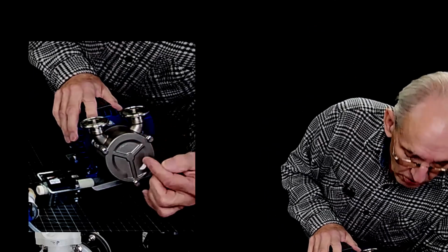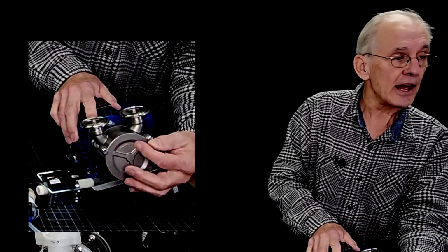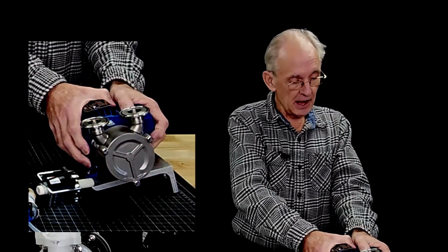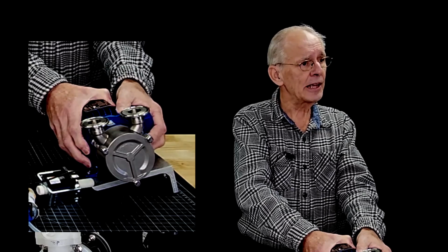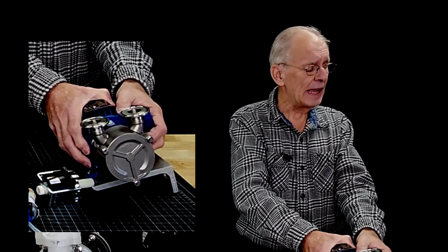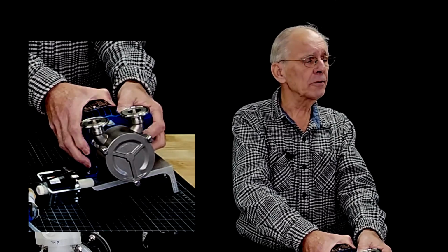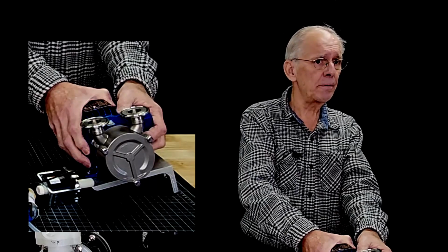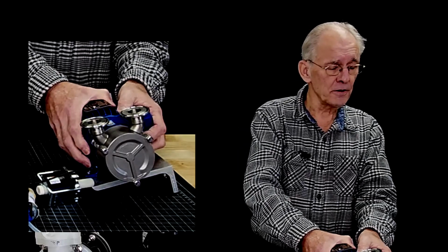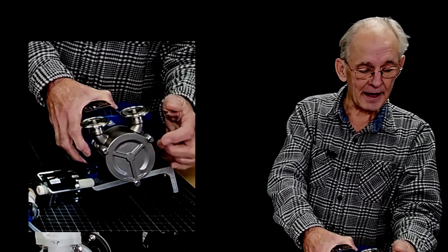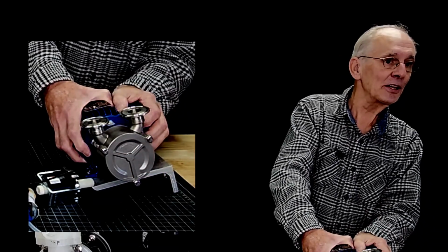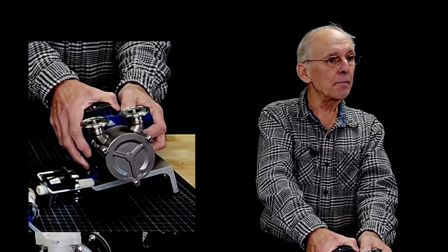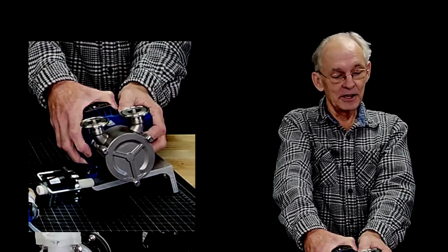You notice the arrow on the end. And this is how I found out about this type of pump. My boss had somebody send him an email saying, hey, I'm working for a pump company, and he sent a picture of the pumps they make. And when I saw the picture, the thing that jumped out at me was that arrow. And I realized that was the pump I'd been looking for more than 10 years to pump permeate from membrane systems.